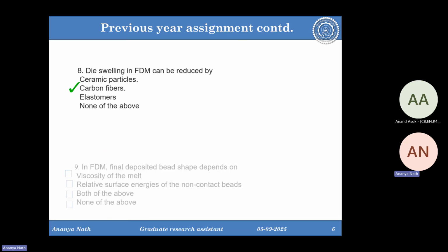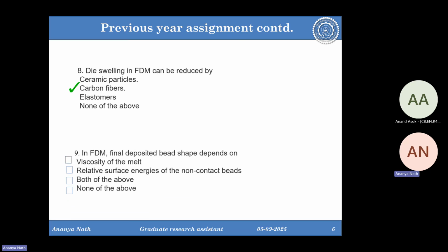Next, okay. The die swelling in FDM can be reduced by carbon fibers, and in FDM, the final deposition bead shape depends on the viscosity of the melt.